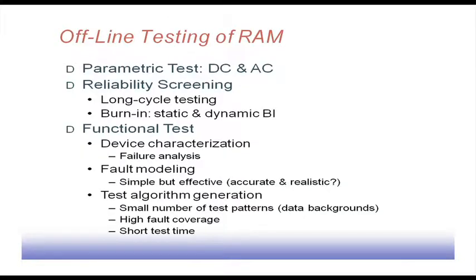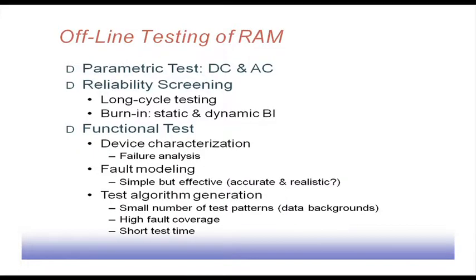Then burn-in. This can be static or dynamic burn-in. Dynamic means it is put into system operation, and static means it is statically tested. This is before it is put into the functional test. We do some testing so that we get some confidence about its operation.